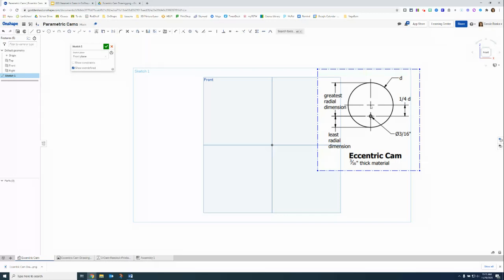So that center marking here, this whole center point, would be the center for this radius or my diameter that I have here for the variable D. Now, normally what we would do is we just do C for center and we draw our center, and then we would type in D for our dimension and add the number. Well, in this case, we don't really have a number because everything is based and modeled parametrically. So what we have to do is actually add in those parameters first.